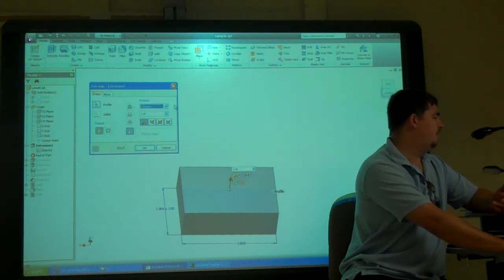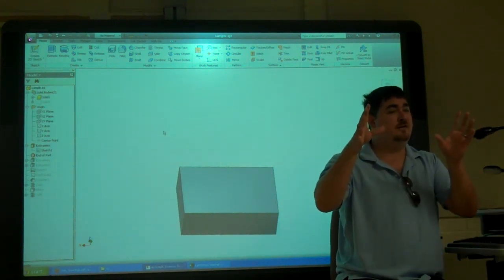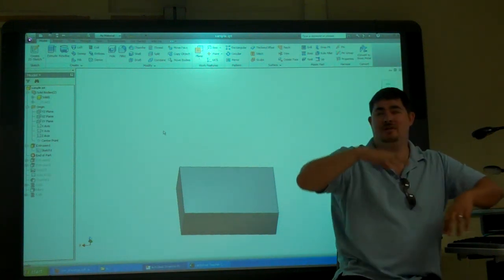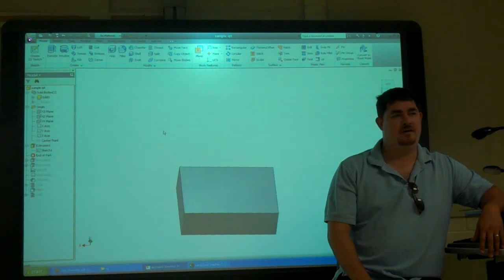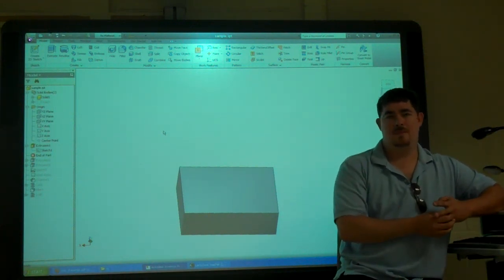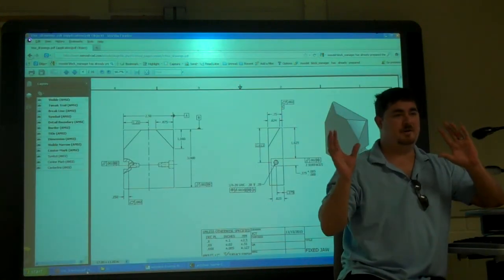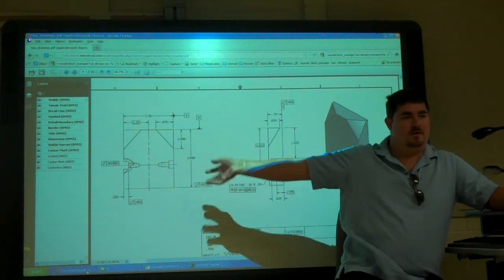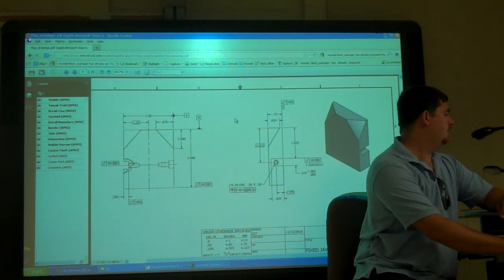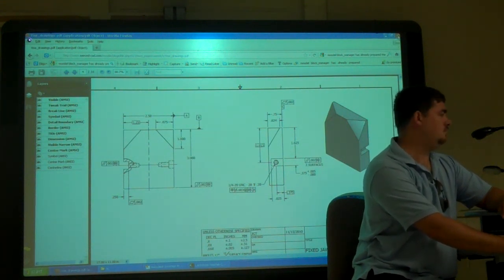If it's a sketch dimension, you can put a tolerance on it in the model. But if it's a dimension that's on an extrusion or something, you can't put a tolerance on it here. So when do you do it? You have to do it in the drawing. In the title block or in the actual drawing? Well, the drawing is what goes into the title block. So we call this whole thing the drawing. Yeah. Okay. So, questions? No?